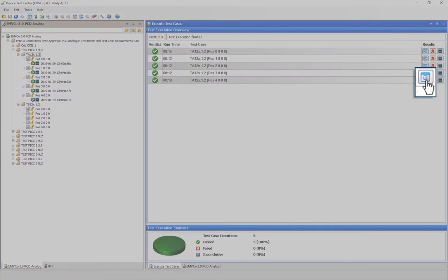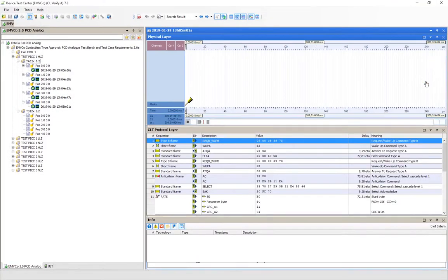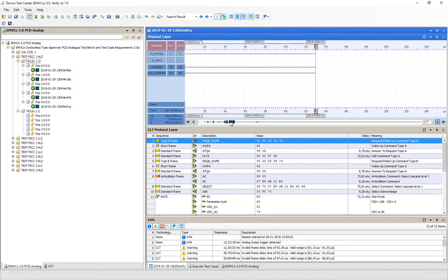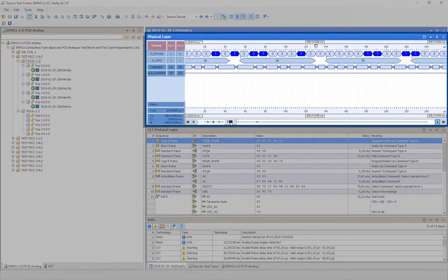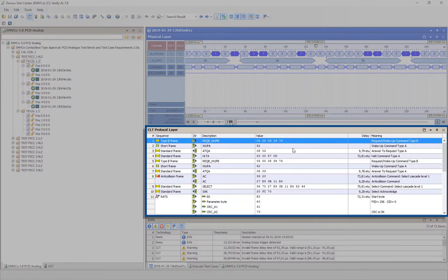Secondly, the monitoring view provides 3 general sections. The upper part displays the digital representation of the analog signals exchanged. It's important to note that you can zoom in and out. The middle section drills down the communication to bytes or even bits exchanged, indicating the origin of signals, reader or PICC simulation.